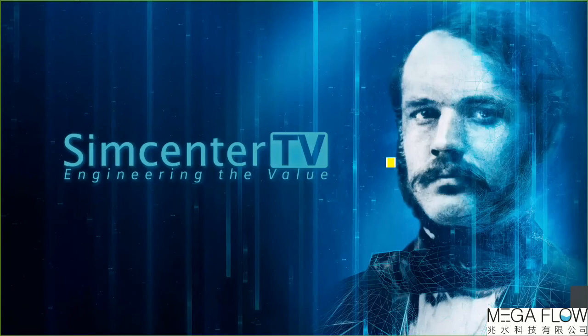So there's a question regarding the DES pragmatic approach. I'm using 1 millisecond of a time step size. Is this using MRF and tangential velocity? Yes, it is. We had a very nice presentation from Maserati during our last Simcenter conference in Amsterdam in December last year. And that's exactly what they did.